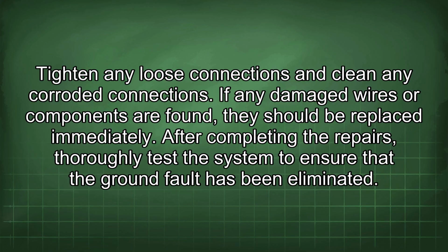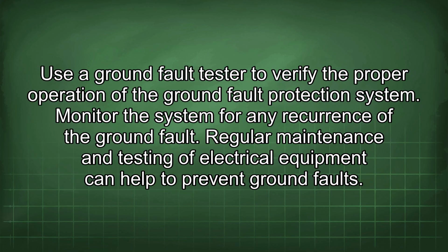After completing the repairs, thoroughly test the system to ensure that the ground fault has been eliminated. Use a ground fault tester to verify the proper operation of the ground fault protection system. Monitor the system for any recurrence of the ground fault.